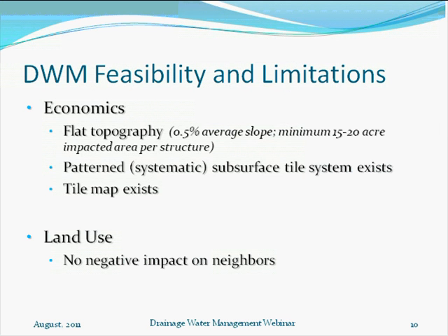Well, before I go on though, it is possible to have drainage water management systems in steeper topography, up to 1%, maybe even steeper. But as I had explained, it does get more expensive, and at some point, it's cost prohibitive. We do need to know where the tile is, and it's important to have that patterned subsurface tile system, as I explained. Otherwise, we're not going to get a significant benefit. And so having a tile map and having a patterned system is important, and a limitation in some cases.